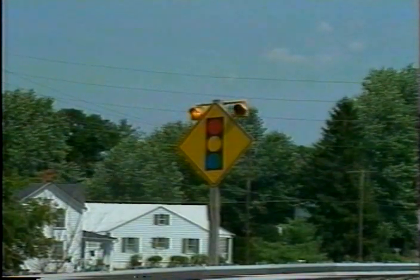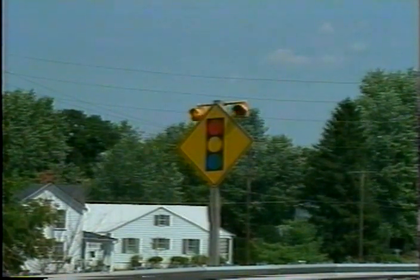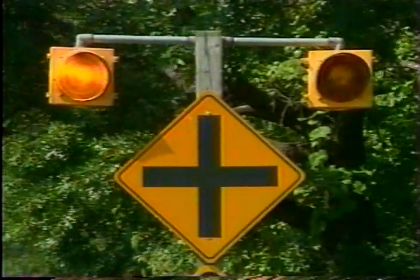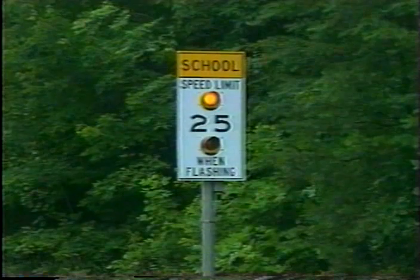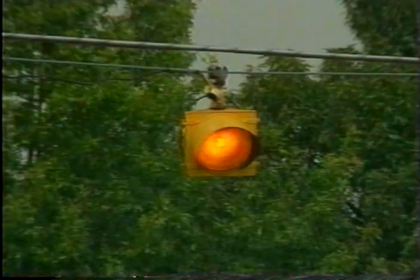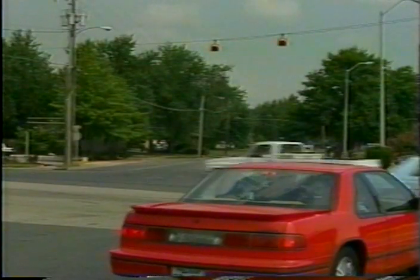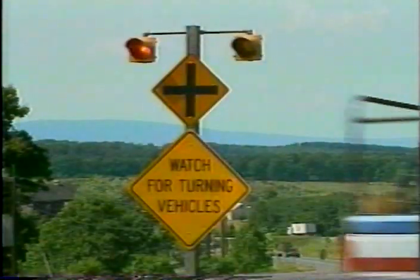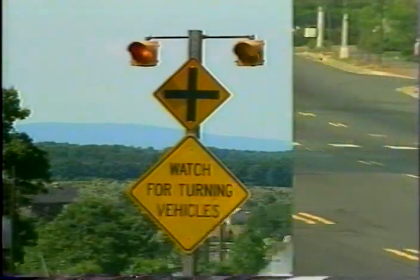A beacon is one or more sections of a standard traffic signal head with a flashing yellow light in each section. The beacon is designed to warn drivers of special situations or to draw special attention to speed limits. It is used as a speed limit beacon or an intersection control beacon. This kind of intersection is one where the accident rate means there is a hazard, but the amount of traffic does not justify a conventional traffic signal. Beacons are used for hazard identification and with stop signs.